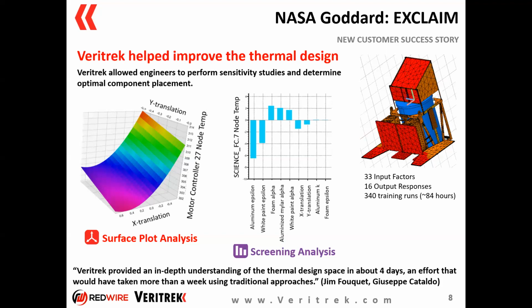And then in the middle portion, they used Veritrek's screening analysis feature to do a temperature sensitivity of multiple scientific instruments that were on board this EXCLAIM model. That's really what the screening analysis feature was designed for, to perform these temperature sensitivity studies. You can see along the x-axis are certain input parameters of interest, and we're looking at how each input parameter impacts our output response of interest on the y-axis. This uses Monte Carlo methods to perform this sensitivity study.